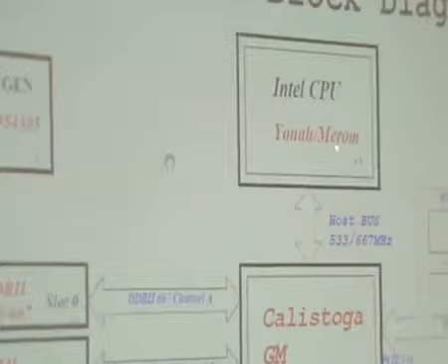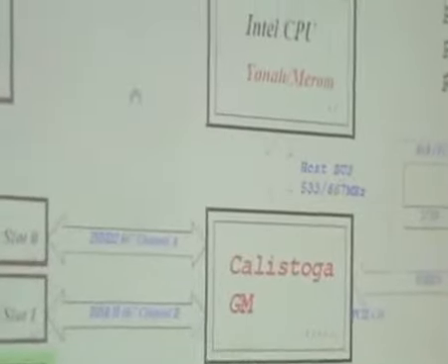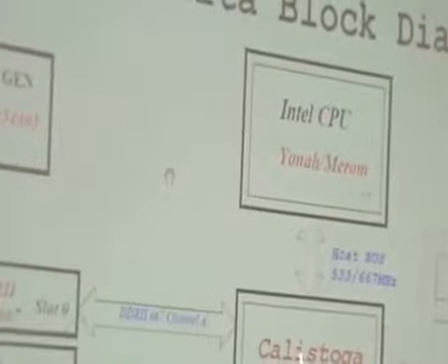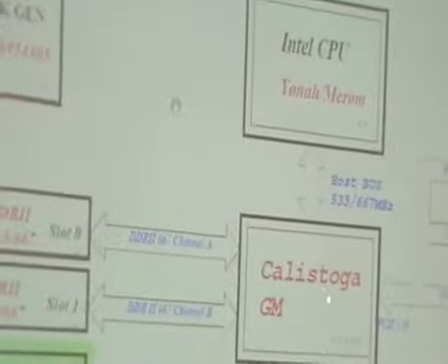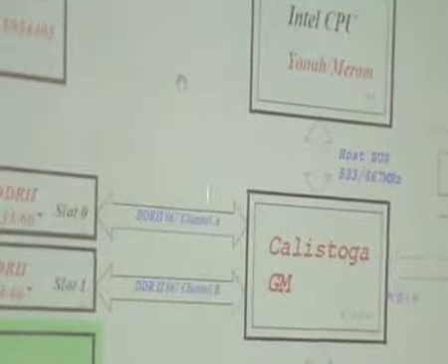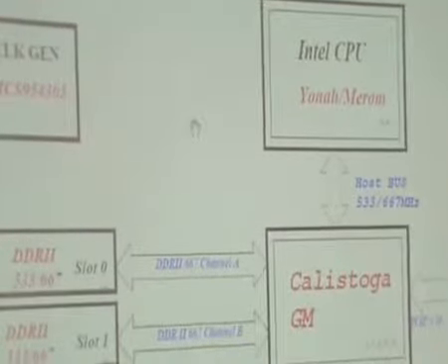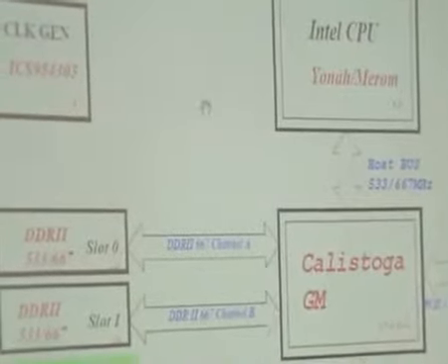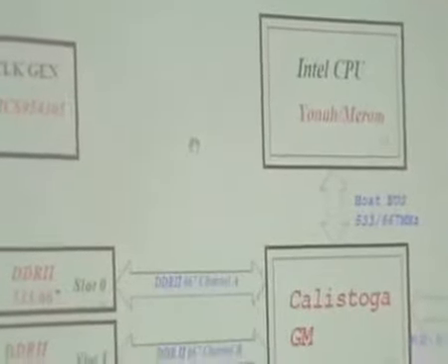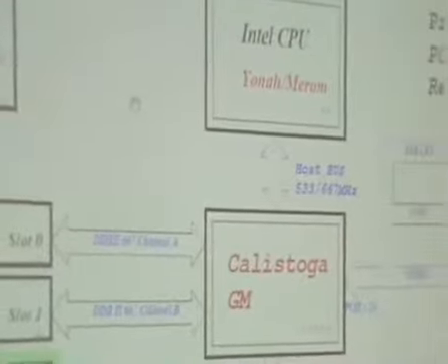Because your other chips like GMCH and ICH are slower. These chips work at slow speed. You cannot afford to run the entire chip at the same speed, because when data moves from your chip to the connectors, if it moves at the same speed as the CPU, the data won't reach there. This data travels through various buses like the PCI Express bus. This is the host bus. So what are these buses? These are physical connections on your laptop motherboard.